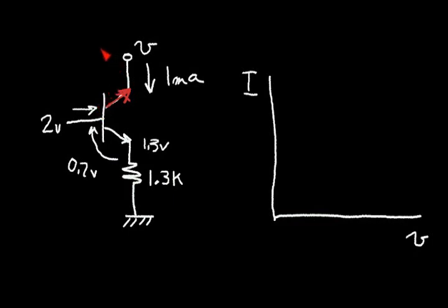And so I could go as low as, say, 1.6 volts for the operation of this current source. And that would give me 0.4 volts forward bias of this diode, which may be acceptable. So this current source is going to have a range, and it can operate above 1.6 volts and provide a milliamp of current approximately. So let's say this is 1 milliamp, and there'll be some variation.